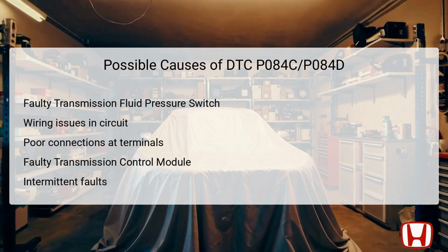not the next. Additionally, the TCM itself could also be malfunctioning, resulting in erroneous signals sent to or from the pressure switch. An intermittent fault may complicate diagnosis, as it may not always trigger the same alert. Ensuring all wiring and connections are intact is essential for correct diagnosis.